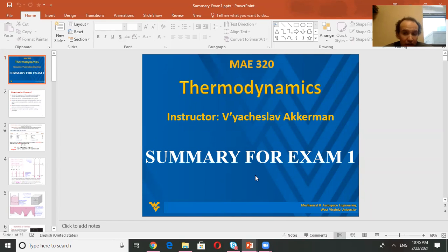So if state 1 is a saturated mixture, state 2 can be solid, liquid, vapor, saturated vapor, or superheated. So for state 2, again, you should be able to solve this problem from the very beginning. Assume it's saturated, check, and show your analysis. To identify the state, you should know two intensive properties. Remember, pressure and temperature, or pressure and specific volume, pressure and internal energy, volume and internal energy, and so on. You should know at least two of them. Please make sure you understand this, okay?